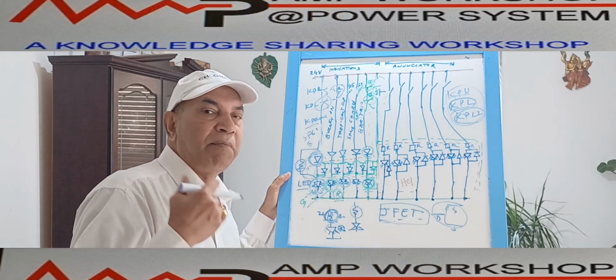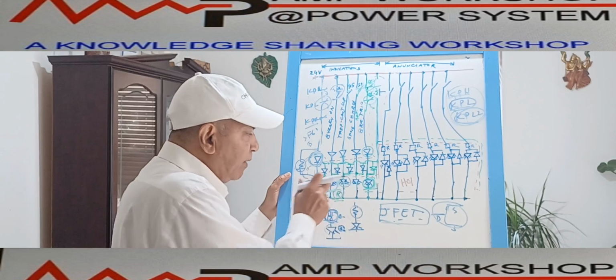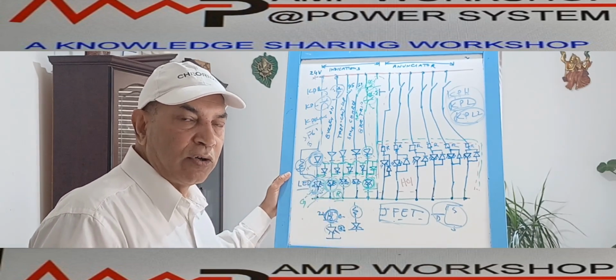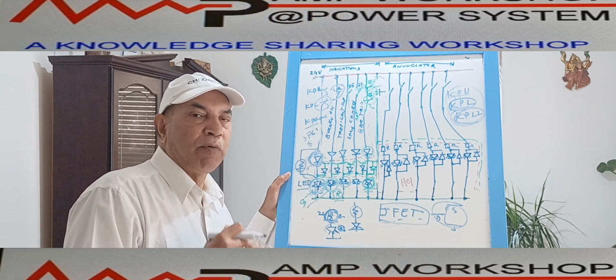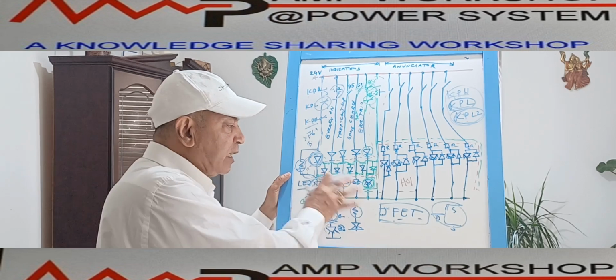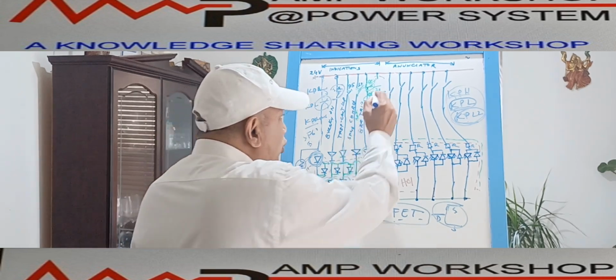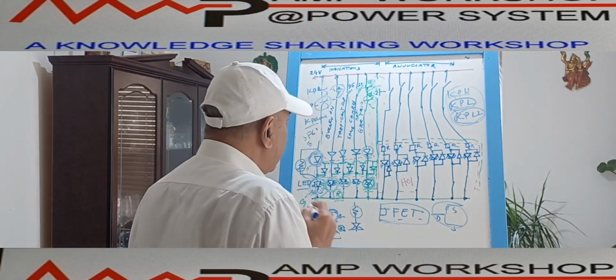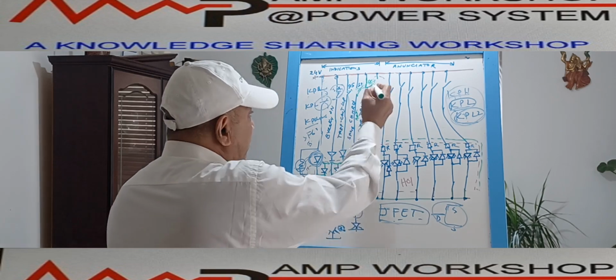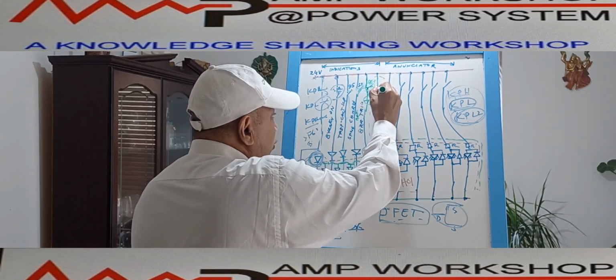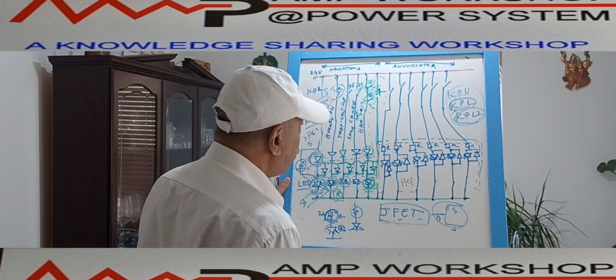That means normally every week you can check this LED's operation. That's why we provide in the switchgear another push button for that test purpose, the LED test push button. That LED test push button we put in parallel to these actuating parameters. In parallel to this, we put one push button.